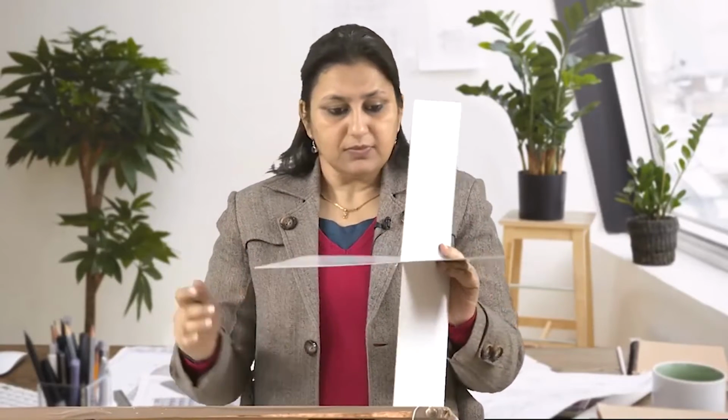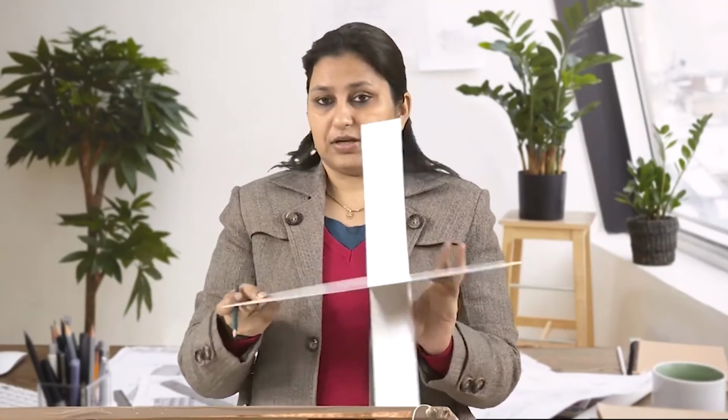Now, let us move on to the second and fourth quadrant. So assume that this same point, which was at 50 mm from VP and 70 mm from HP, is now located in the second quadrant. So if the point is here somewhere, what happens if we fold it? Both HP and VP have gone to the same place. So now in this case, we will have nothing below the XY line, the reference line. Both the planes, the HP as well as VP, have merged together to go to the top.